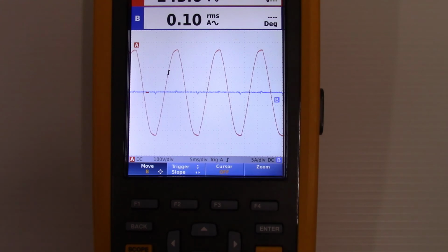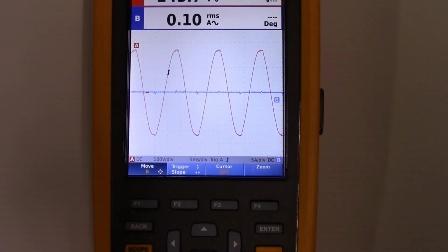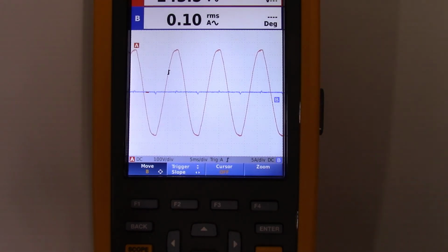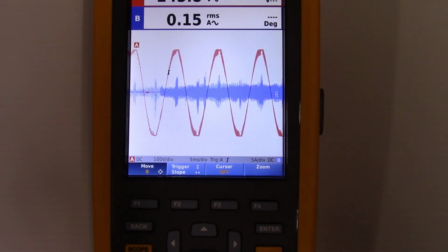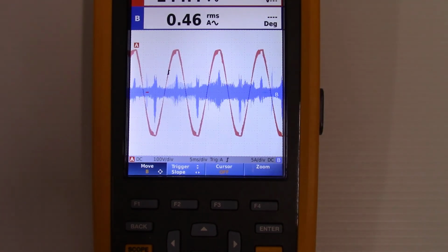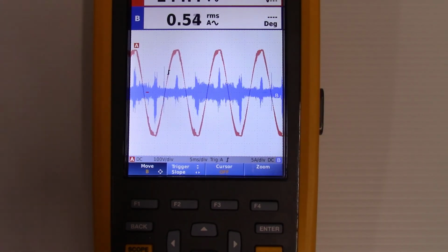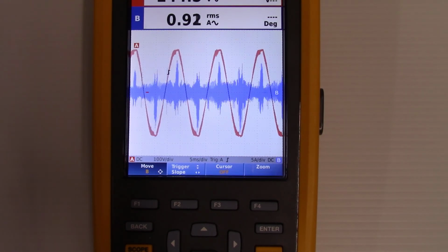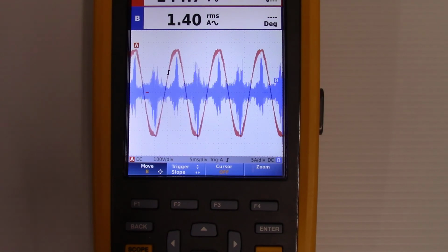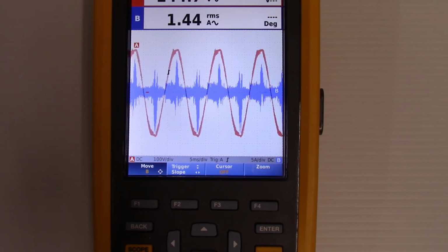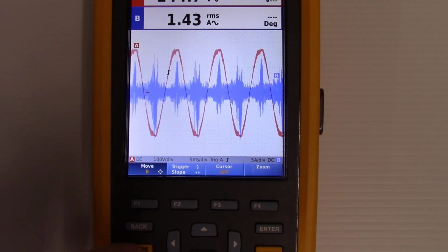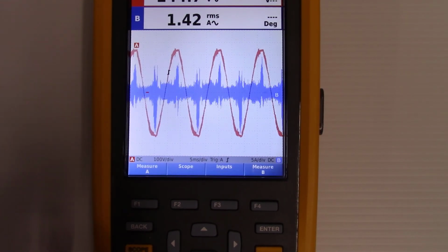Now we are going to get a visual on an AC drive, so a non-linear load. I'm going to start it up. You're going to notice something completely different. It's ramping up. It's connected to the same 240 volt source. Now you'll notice that the waveform looks really thick and noisy, and what we can do is go in and apply what's called smoothing.